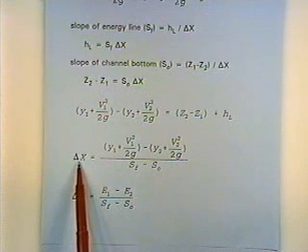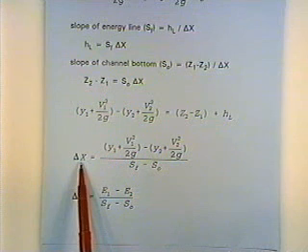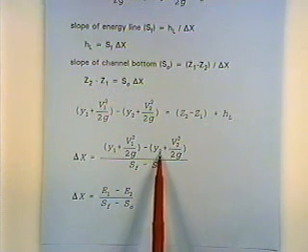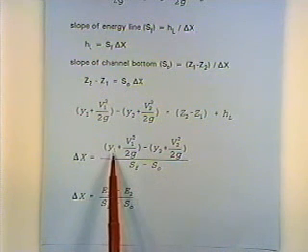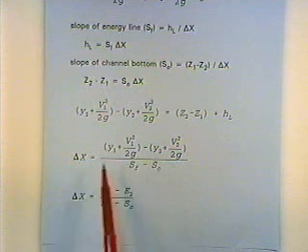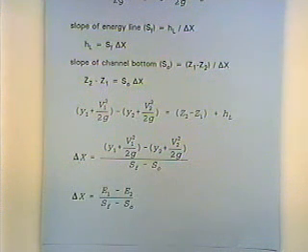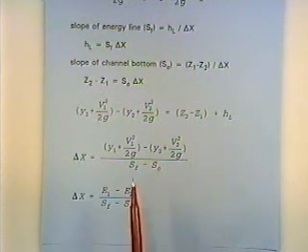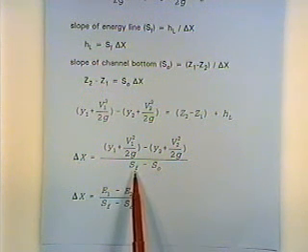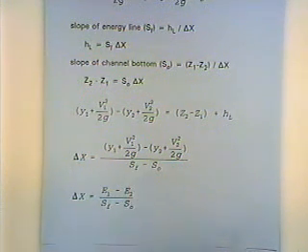We'll compute the horizontal distance between the 10-foot and the 9-foot depth. Then we'll do it all over again. We'll plug in 9 feet for y2, 8 feet for y1, and just keep plugging into this equation over and over again. Of course we'll have the friction slope term, and we'll be using the Manning's equation to solve for that.